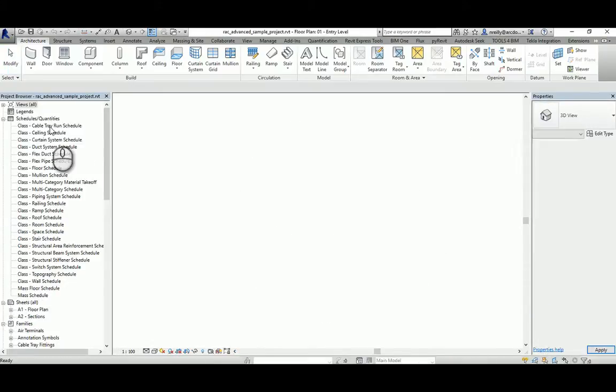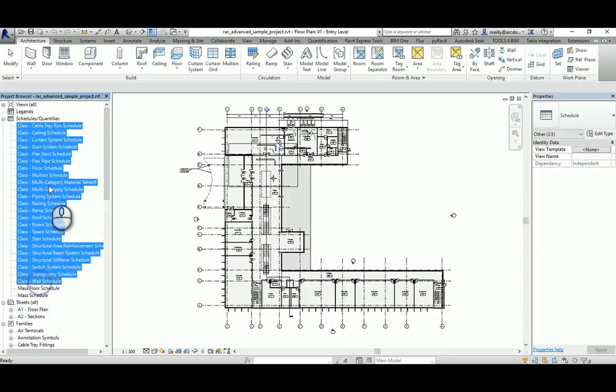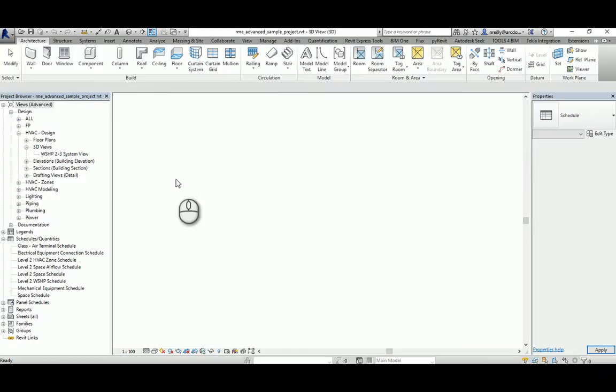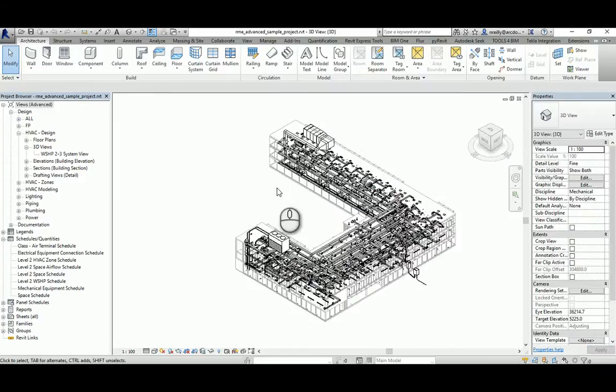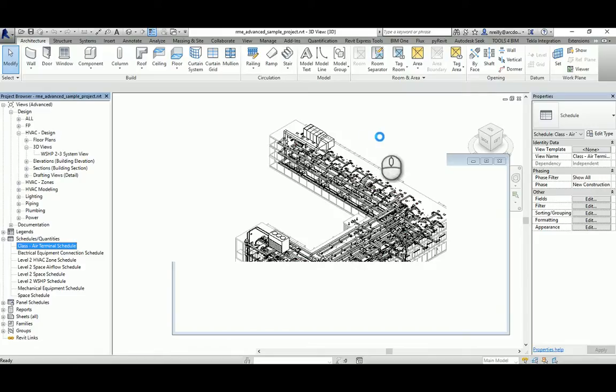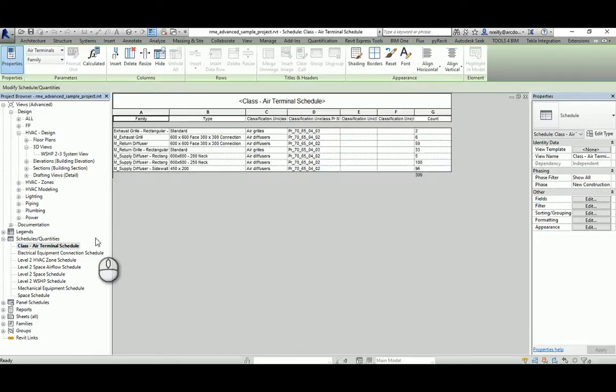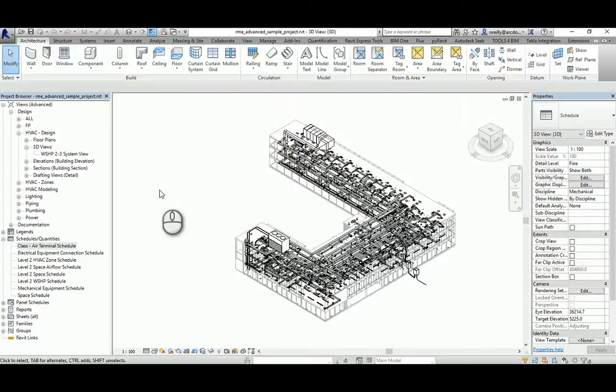I'm going to skip back in. I can highlight all of them, and I'm going to take off the material one for a sec. Okay, I'm going to Control C. It's that simple. I just hit Control C, and the trick when you're in this project is to make sure you're actually in a view. If I go into this schedule view here and then click here and paste, nothing happens. I have to be in an actual view of the model, so a graphical view.